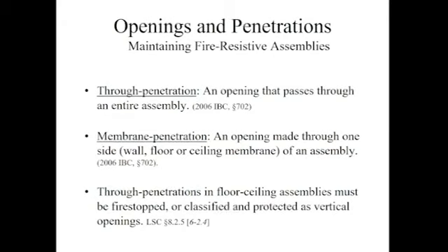Everything that's been tested, either fire stopping or these fire resistive assemblies, the manufacturer gave instructions to the testing agency to describe exactly how to build the assembly, or to build the fire stopping assembly, or what product, how to build it, what manufacturers and products, and how far apart things are, and how long the screws are in the gypsum board, and how the joints are treated, how they're not treated, how's the insulation. All this stuff is instructions to the people that tested it.